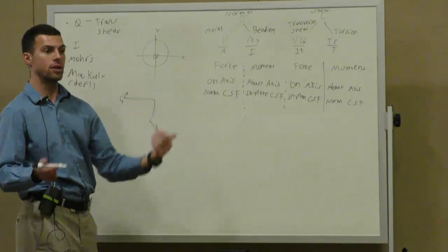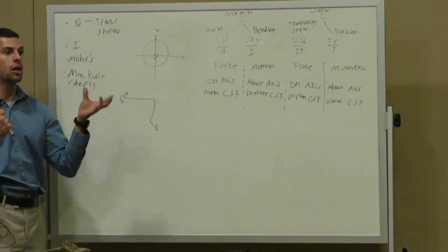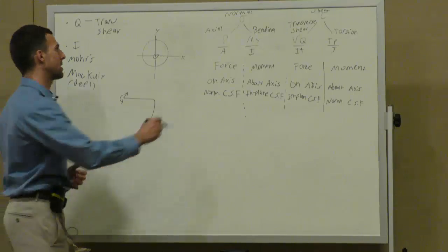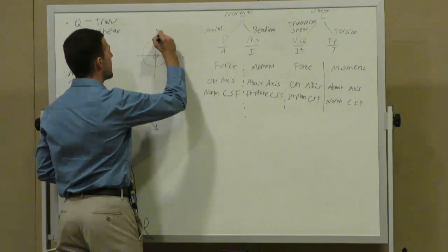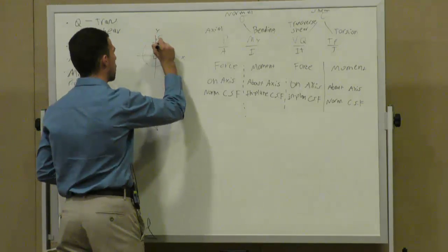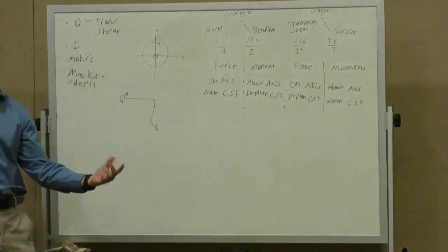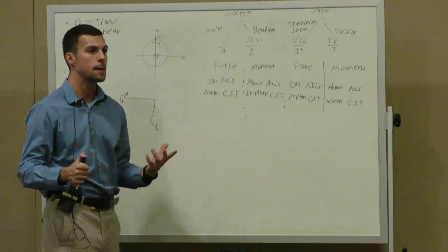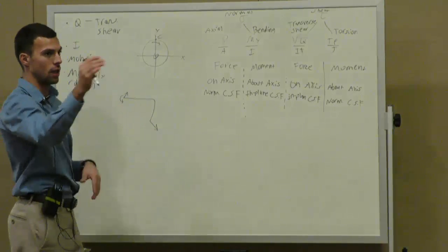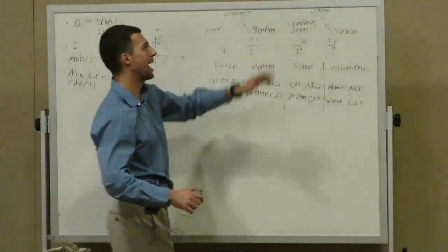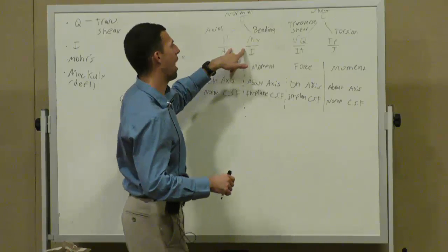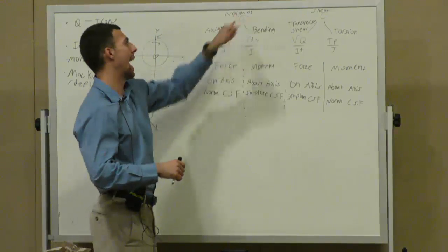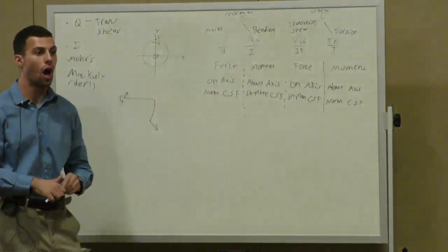And again, the thing with that is you have to establish a directional system, because a transverse shear this way and a torsional shear this way are in opposite directions. So you'd subtract them to find the overall magnitude. Does that make sense? But yes, that was a good question. And yes, if you have both of these at a point, you can add their results up.